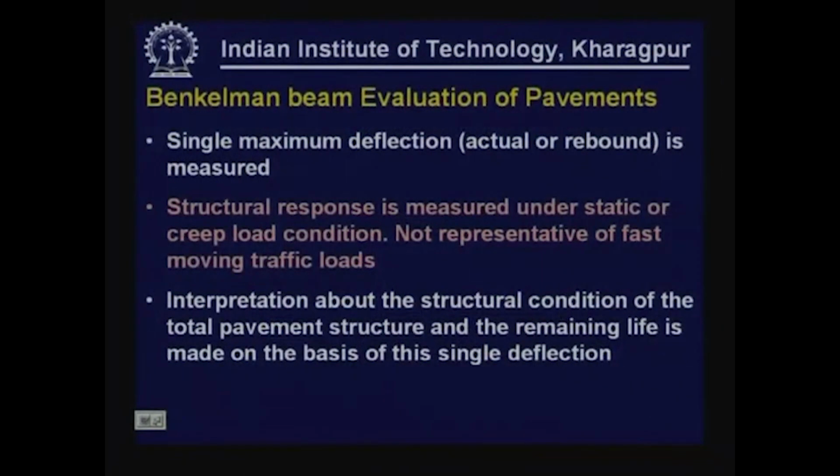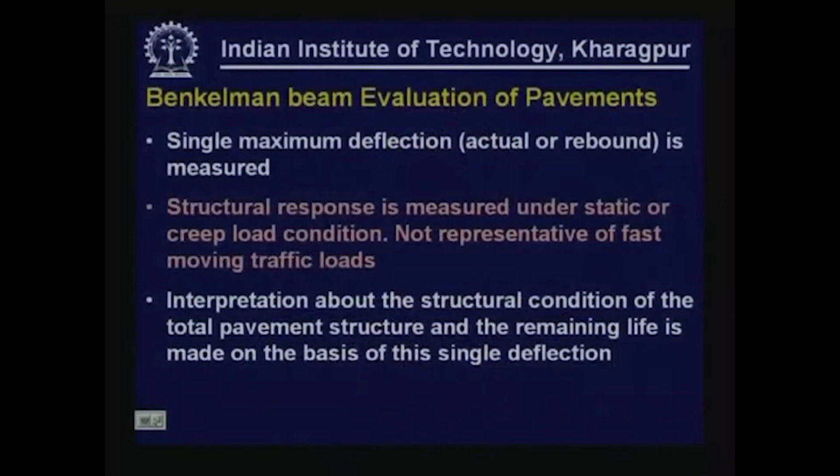Such structural response is measured under static and creep load conditions. This is the problem, because the actual loading condition applied on pavements is by fast moving vehicles. Loading time is very short, so the loading that we apply using a Benkelman beam procedure is not very realistic. The interpretation about the structural condition of the total pavement structure and the remaining life is made on the basis of one single deflection. We have only one deflection available to us. On the basis of this, we have to interpret the complete pavement structure.